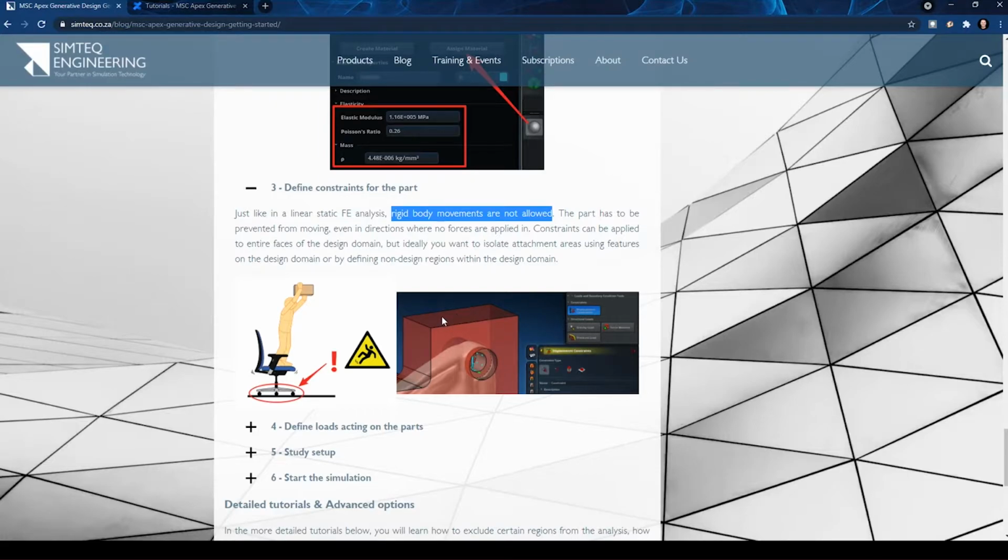Another interesting thing about Apex Generative Design is that these loads and constraints can be applied to any face of a solid, but you can also define solid sections, which we call partitions. Now, these partitions are the exact same method used for general structural analysis in Apex when we define, let's say, hex mesh and subdivide solids into partitions to have the different sweep directions match one another.